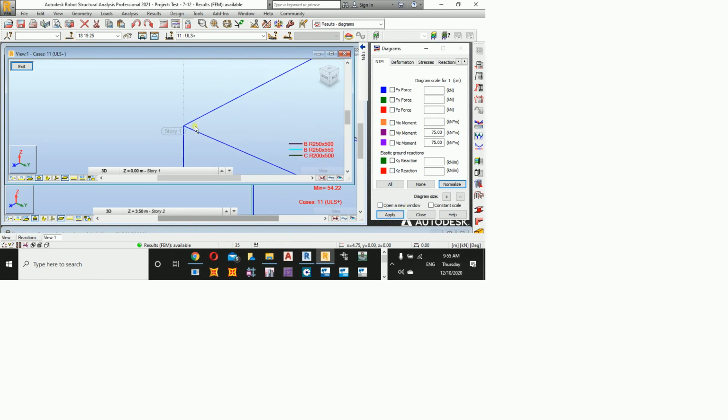Can you see this column is connected to two beams? Now, this beam is going to have bending moment. It's like we are talking about this column. Okay, this is my column. This is the beam coming from here. There is another beam coming from here. This beam is going to have a moment. This beam is going to have another moment. So there will be two moments. One is from this beam, another one from that beam. And this is what can be shown here.